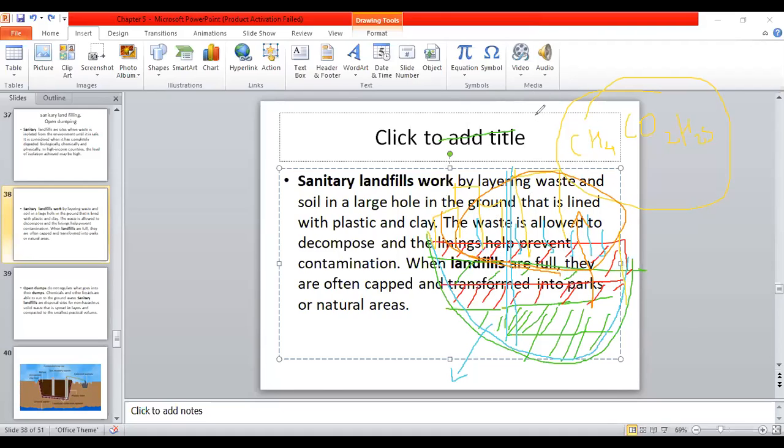So with that note, it was decided to change the design for sanitary landfilling, and hence the scientists decided to go with the provision of vent pipes to collect the leachate. This is the first thing, and at a higher level, intermittently, you can provide vent pipes to emit the gases which are going to be produced during the decomposition process of this solid waste. This is what sanitary landfilling is. Okay, so in my language I have explained.